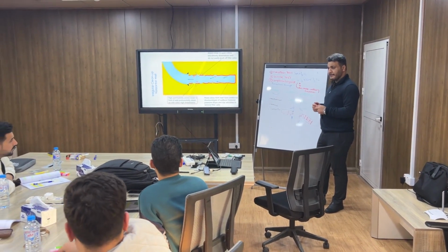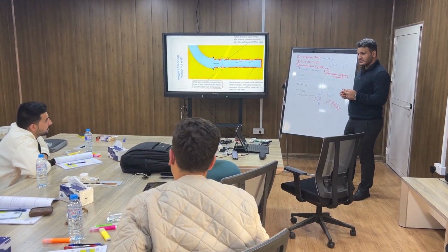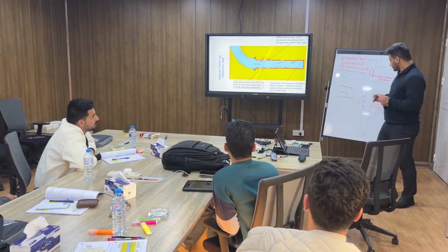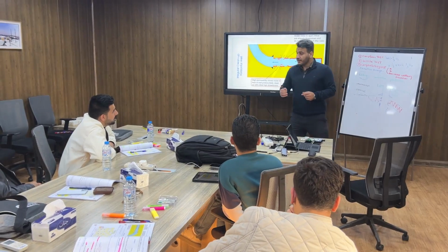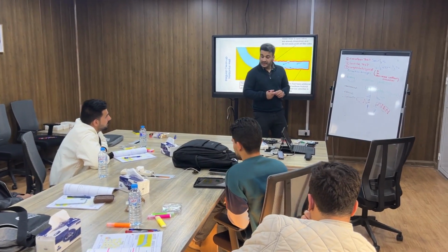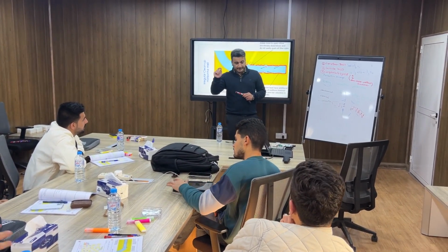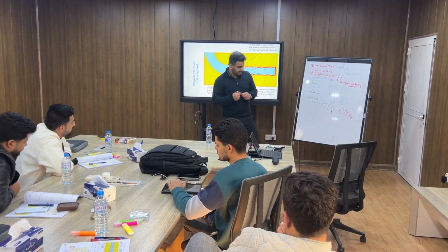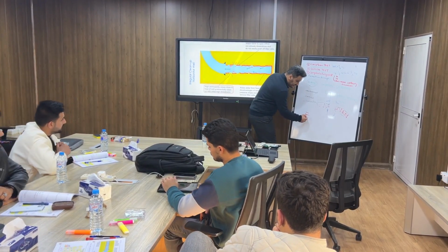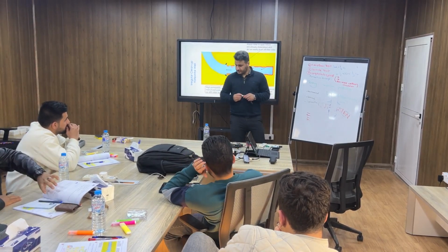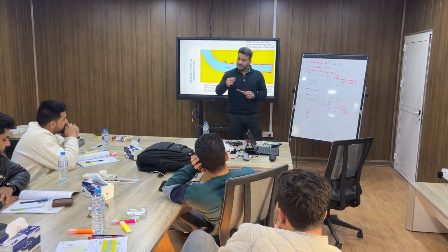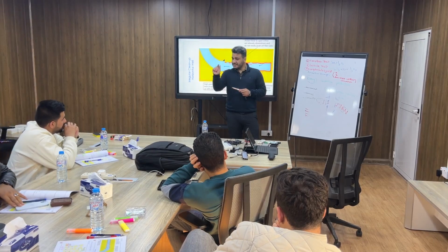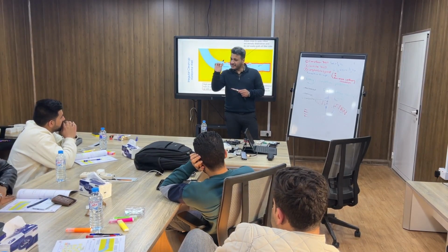What is the difference between a normal lost circulation and this fracture? How do I know about the different types? If we have just a natural fracture, a very small fracture, we use the normal LCM because it is very thin, and it's closed by the LCM.